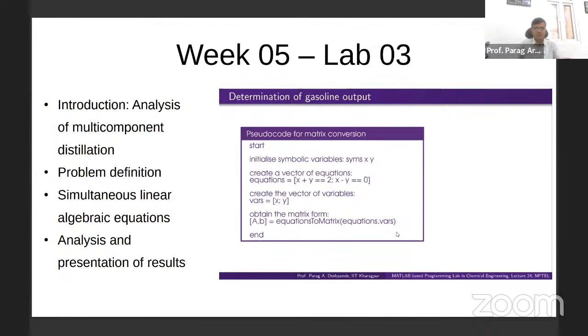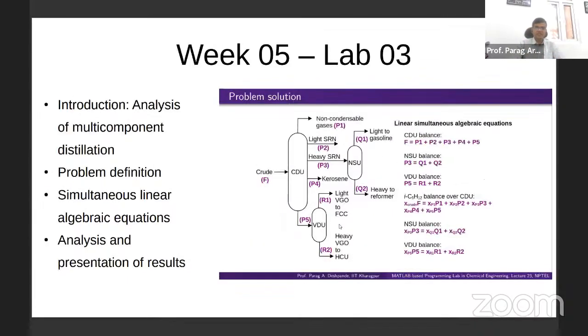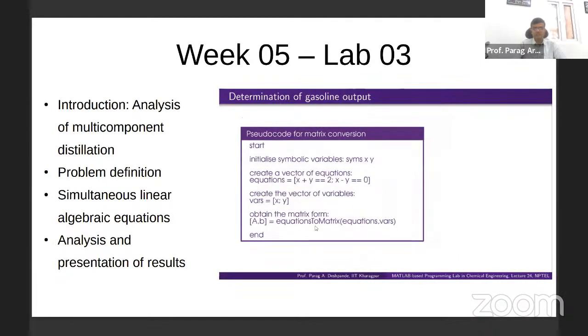You have a symbolic mathematics tool available in Matlab, and you invoke that by SYMS X, Y. Define these variables, and you use the function equationsToMatrix, which means you give equations in a written form, something very similar to what you write on paper, and then this function converts that into the form of a matrix equation, and then you can again solve.